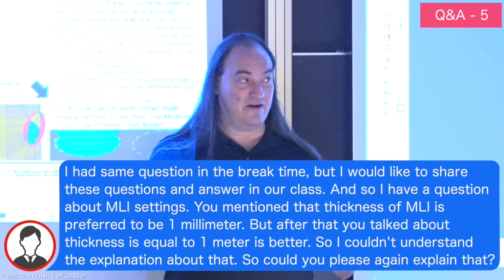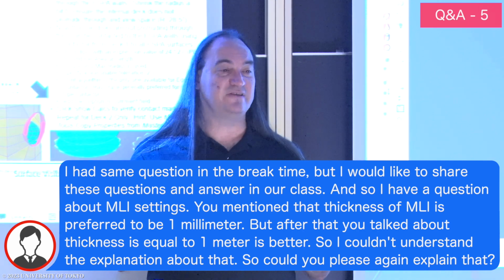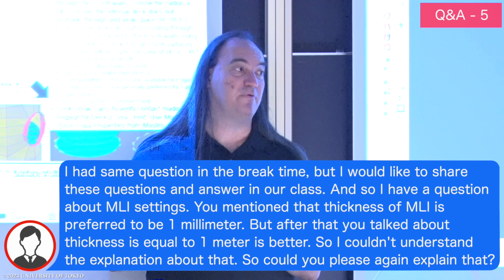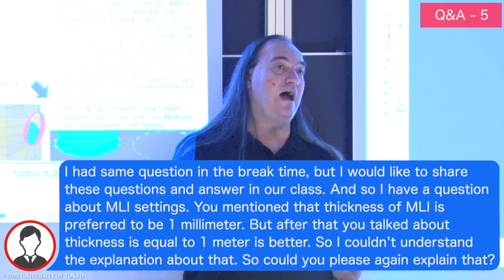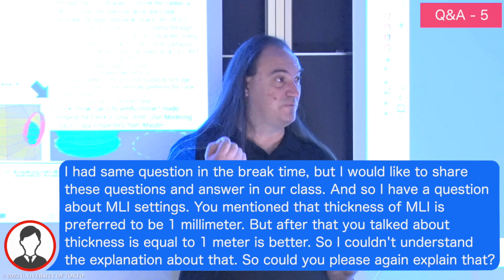I can't take the area multiplied by density to get a mass because I'm off in the units. So it doesn't have to be 1 meter, but whatever you have selected for the density for your material property for MLI needs to use the same thickness that you're applying there. So when I think of MLI mass, I think of it in terms of it's 0.6 kilograms per meter squared. That's my rule of thumb.